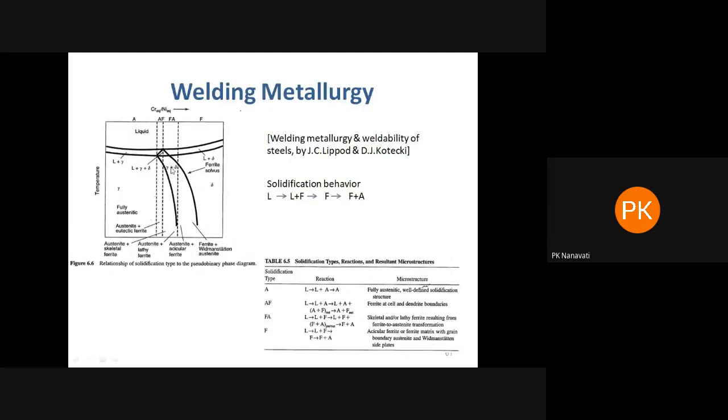That is most of the time for the higher chromium and balanced nickel, that is this region. And some composition cools as not austenitic, but obviously duplex. This will solidify from this region F. So you can understand how this diagram is helpful, and how the various solidification modes are developing.